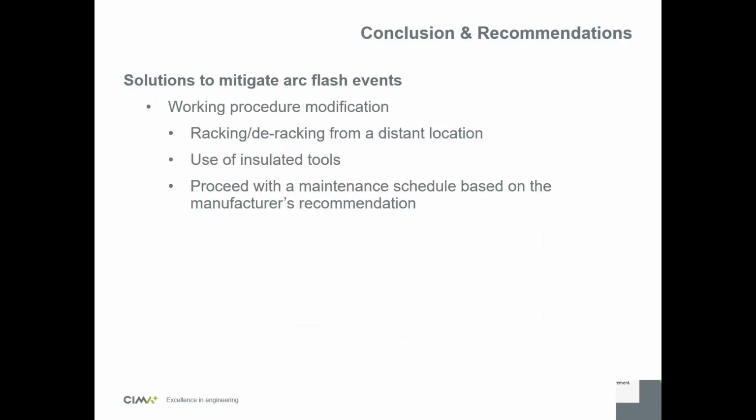And also some working procedure modification tips. You have the possibility of racking and deracking from a distance location. You have the possibility to use insulated tools. And also you need to proceed with a maintenance schedule based on the manufacturer's recommendation.